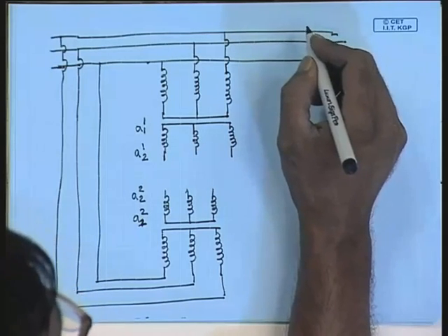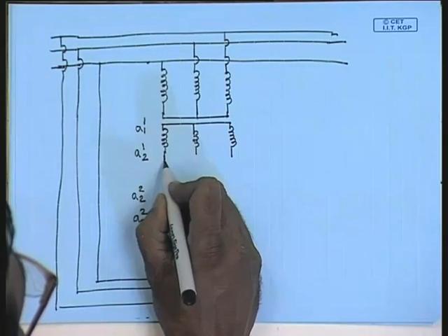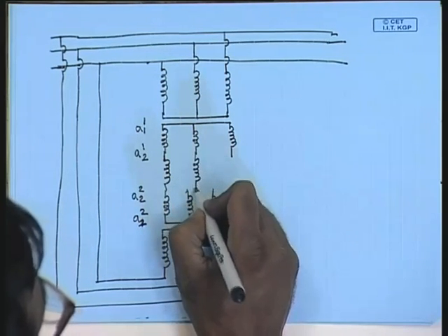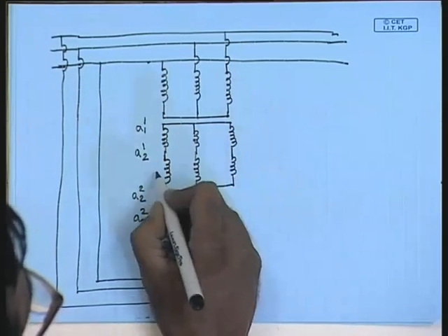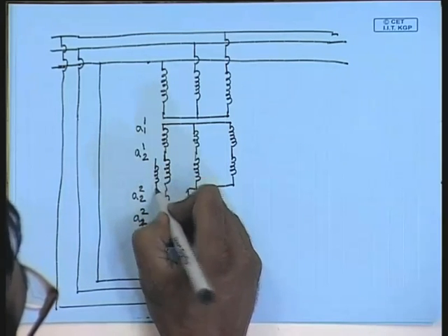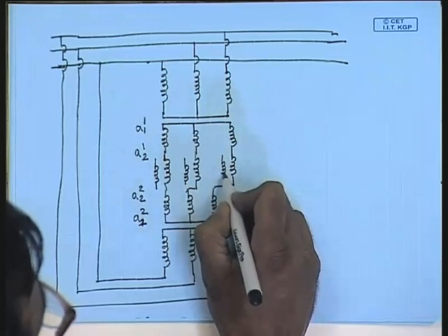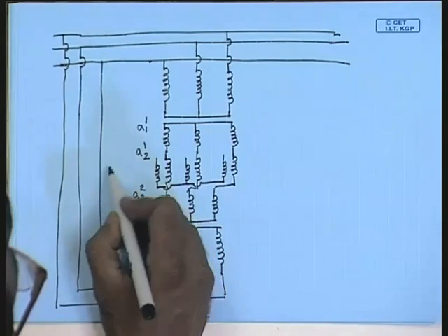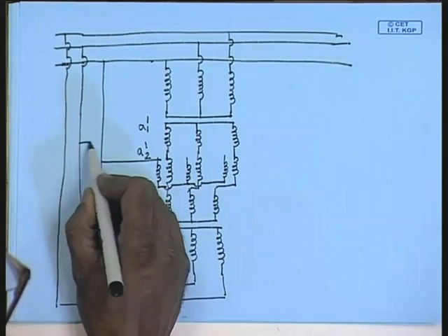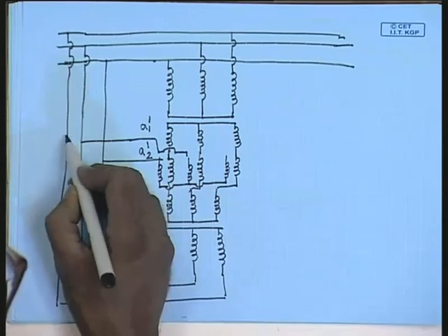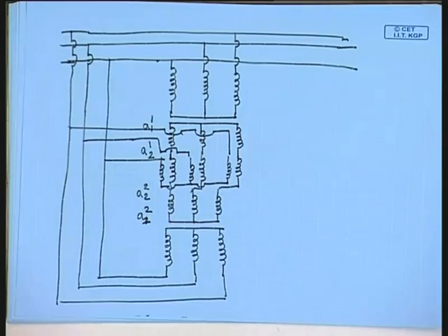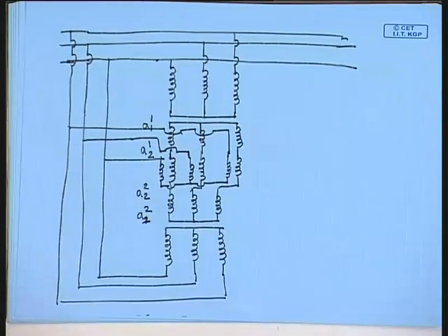However, how do we apply the auxiliary voltage here? For that, we will need a separate transformer. A separate auxiliary 3-phase transformer will be necessary. So, in order to supply that, we will supply it from an auxiliary transformer like this. It will not be a variac anymore, it has to be supplied from a separate 3-winding auxiliary transformer.